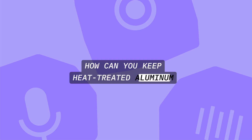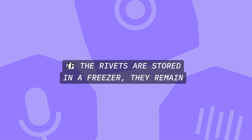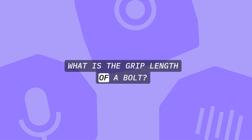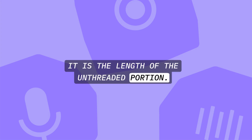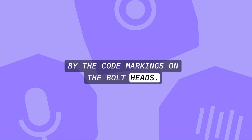How can you keep heat-treated aluminum alloy rivets soft enough to install after the quenching process? If the rivets are stored in a freezer, they remain soft for several days. What is the grip length of a bolt? It is the length of the unthreaded portion. In what ways are AN standard bolts identified? By the code markings on the bolt heads.